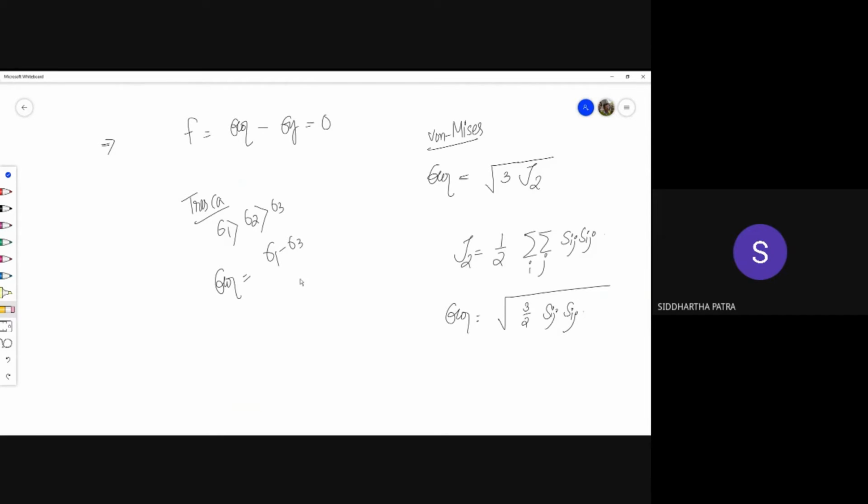So sigma equivalent is actually sigma 1 minus sigma 3. So you see, by 2 is the maximum shear stress, and this is the tau max. And this tau max must go to tau y for yielding. Now sigma y is twice tau y. So basically the sigma equivalent would be twice tau max.